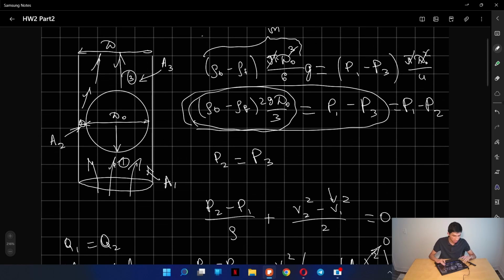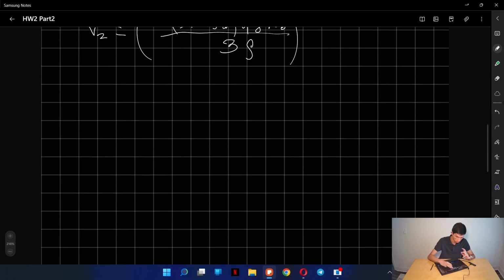In this specific example, if we assume our tube to be straight, there's going to be only one velocity at which the ball is in a force balance. So it's not how a rotameter actually works, because we need to measure the velocity using the height of the ball, but here there's one specific height and one specific velocity for the force balance. But that's not what we actually want, right?